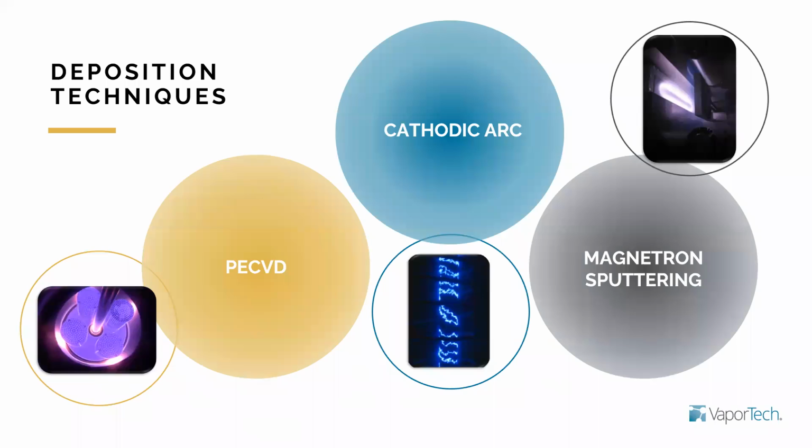You have those metals coming out of the target, and then they combine with the gas that you're using. That can be nitrogen, oxygen, or a carbon base, such as methane and acetylene, and then form the coating. And in terms of the PECVD process, you don't have a solid source. You have either gases or liquids that are introduced in the chamber, and they become the coating itself.